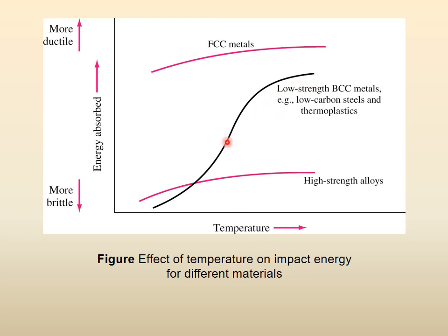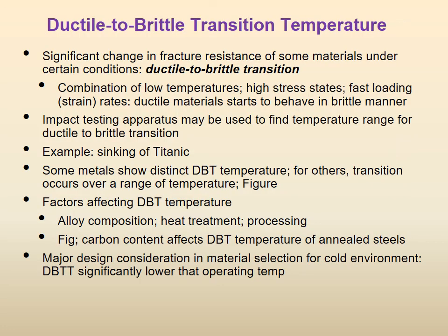These materials are ductile and brittle depending on the temperature at which you are applying the load. So the ductile to brittle transition happens, and therefore once they become brittle, they can still take a lot of load if it is a regular load, but if it is an impact load, it is a hammer load, and now they have become brittle, then they will easily fracture. So that is what I was trying to explain here. This is already explained to you, but we will talk about a little more, of course, as we always do.